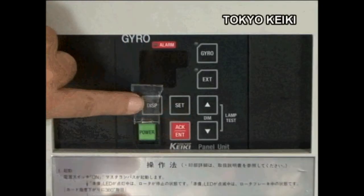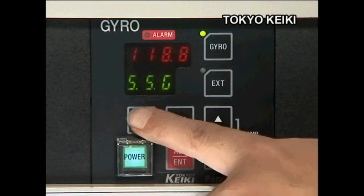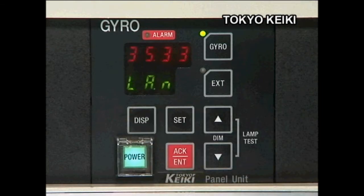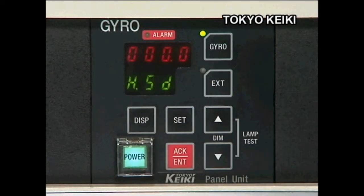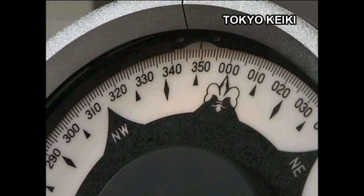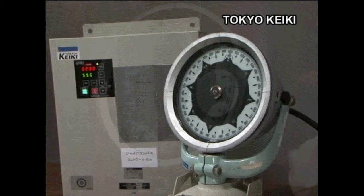For the gyro compass made by Tokyo Keiki, turn on the main power switch. Check the ship's position, latitude, and ship speed, then set the starting azimuth. If a discrepancy between the indication of the gyro compass and that of the repeater compass is discovered, adjust the repeater compass.